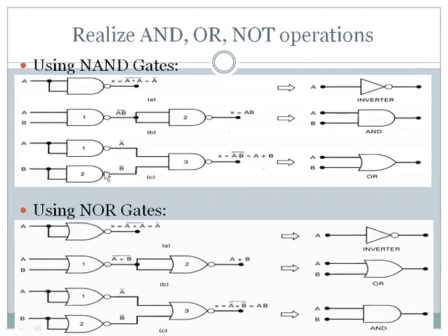And for the second NAND gate, we have given both the inputs as B. So it also performs the inverse operation, and the output will be B bar. And these two outputs are given as input for the third NAND gate. So the output of this third NAND gate becomes X equal to (A bar dot B bar) bar.